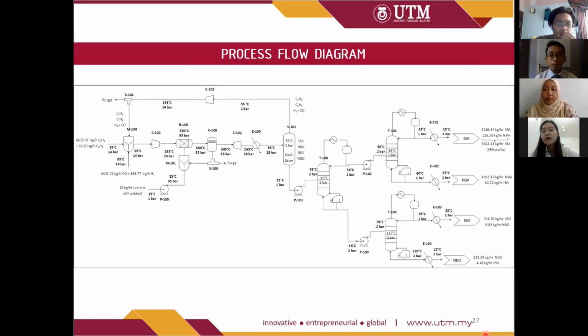It means your PFD is not complete. Can you do a mass balance and energy balance without taking into consideration the treatment of the gas you want to push or discharge as wastewater? Where is its unit? For the others you have specifications, valves, pumps, everything. That's very large equipment, not small. Okay, so make sure you include that.